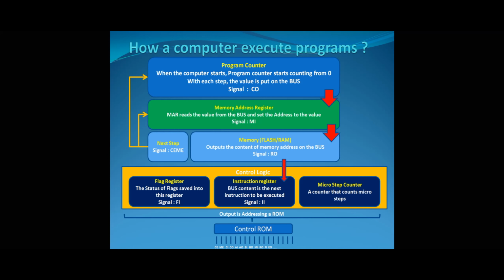Now, whether this memory is the flash or the RAM chip, it doesn't matter. The point here is that we are addressing some sort of memory. Now, in case of Bravo, we have the circuit designed in a way that when we start the computer, when we're pointing to address 0, that's going to be pointing to our flash. Normally, you would be pointing to a flash memory or an EEPROM so that you could boot the computer using some instructions at the beginning.